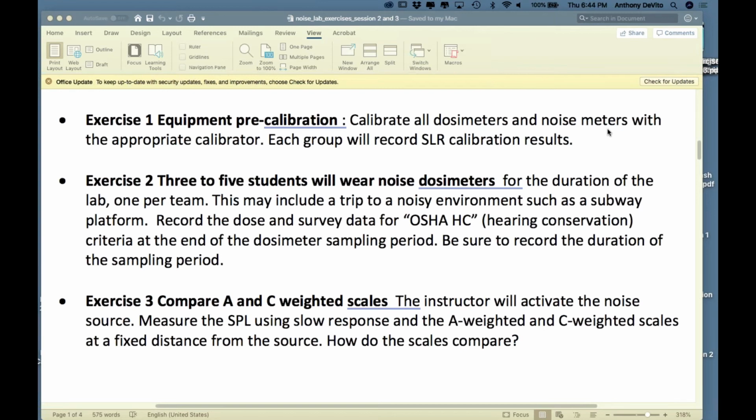Me blowing on my hand is far more pressure than is involved in the sound that we're listening to. So wind or a lot of air currents can really throw off our measurements. That's why, unless it's really pretty much still air, we'll use a wind collar.